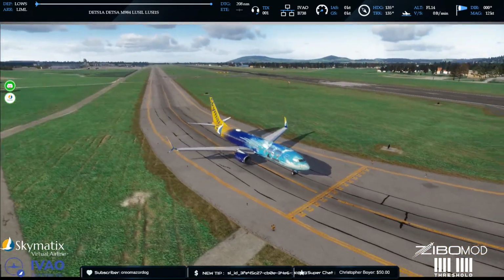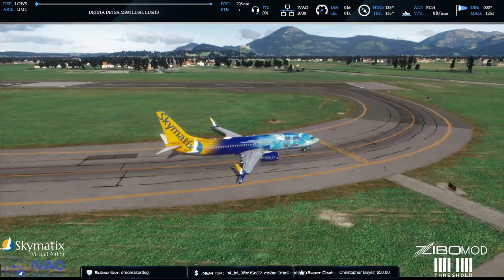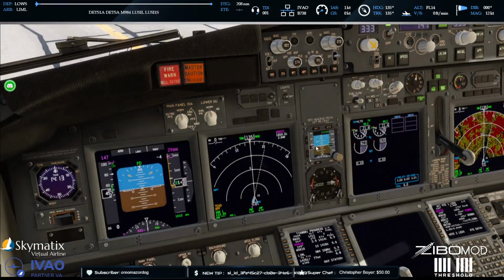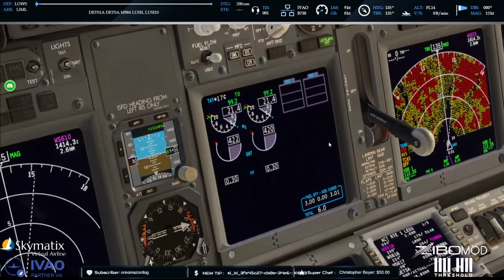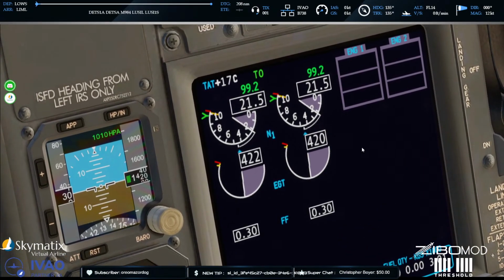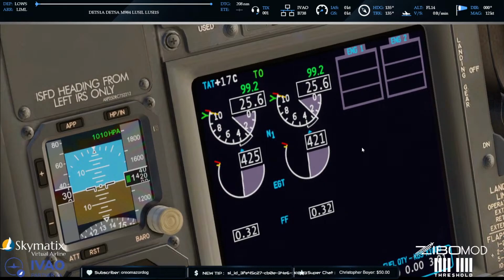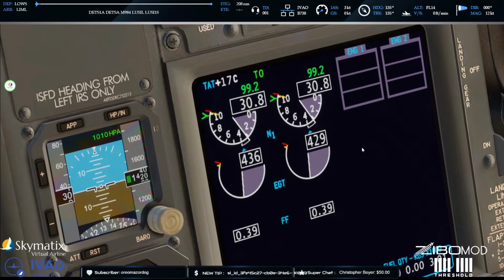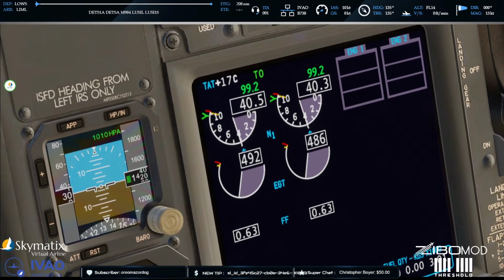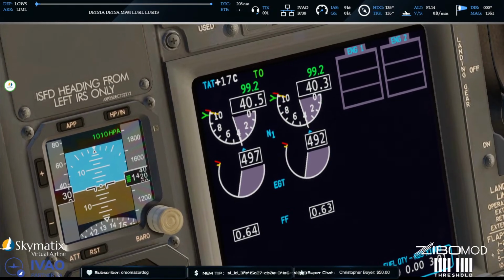Jet power, I agree. Before you join the runway, Nico. Yeah. Because the winds will be different. I'm wondering whether you want to try going to 40%. We might as well. Right, so I'm going to take it to about 40%. Oops, that's too much. All right, so watch the EGT, it rises, and then it's supposed to fall back. And if it doesn't, it means he hasn't looked at that code yet, and I was under the impression he did. Let's take it back.